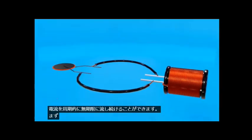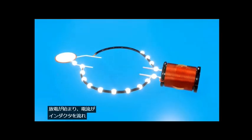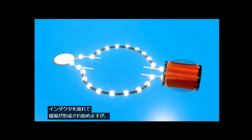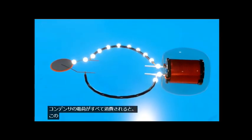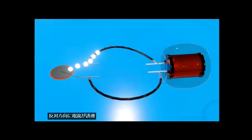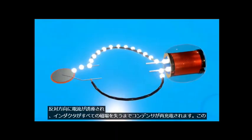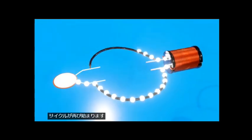Let's suppose that initially the capacitor starts to discharge, and by doing this a current will go through the inductor, which will start to form a magnetic field. But when all the charges of the capacitor have been used, this magnetic field will begin to lose its strength, inducing a current in the opposite direction and recharging the capacitor until the inductor loses all its magnetic field, starting the cycle again.